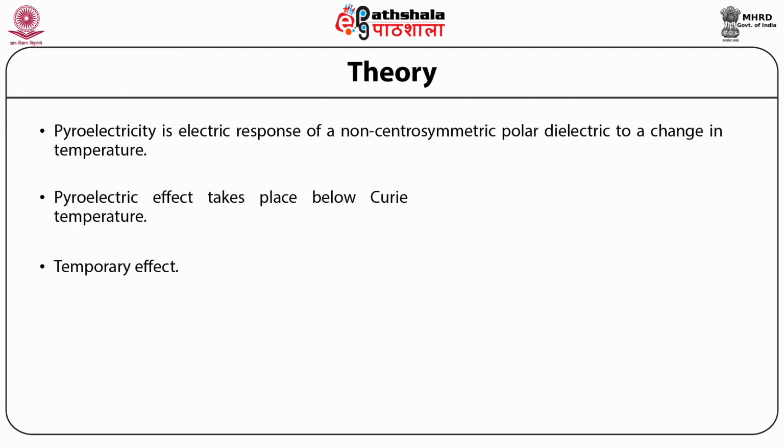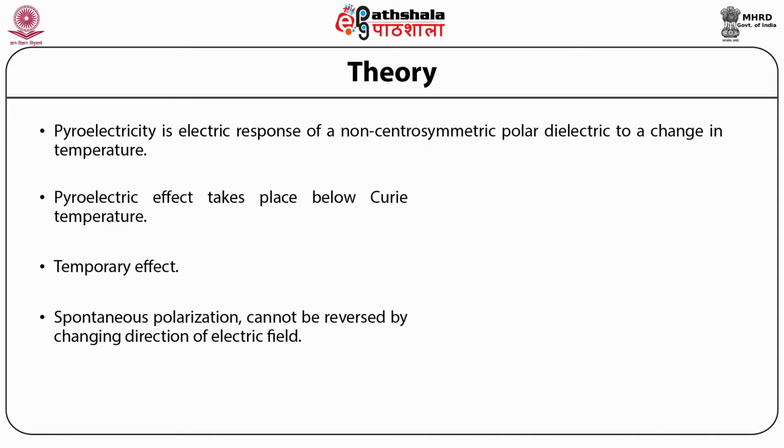This effect is temporary. If the temperature stays constant at its new value, the pyroelectric voltage gradually disappears due to the leakage current. Within the same temperature limits, the charges developed by the effect of heating or cooling are equal and opposite. Pyroelectric materials exhibit spontaneous polarization, that is, polarization in the absence of electric field, which cannot be changed or reversed on applying electric field. It does so in ferroelectric materials. All pyroelectric materials are also piezoelectric. However, some piezoelectric materials have a crystal symmetry that does not allow pyroelectricity.